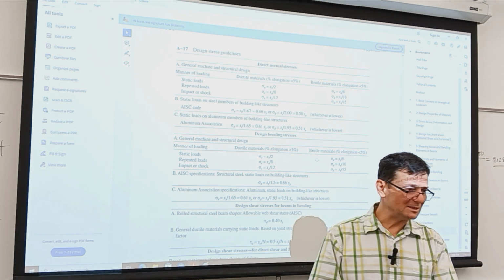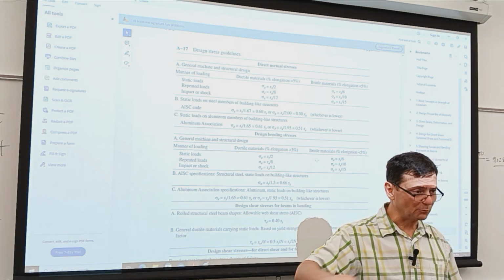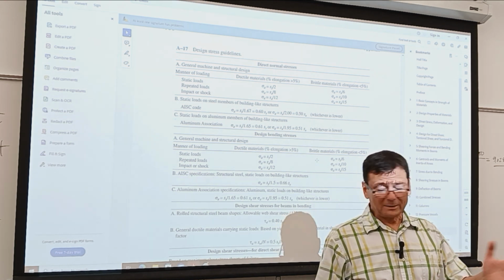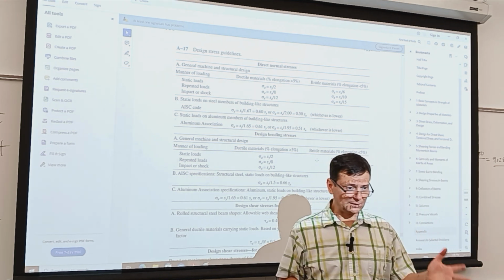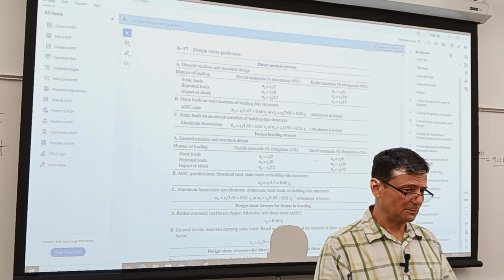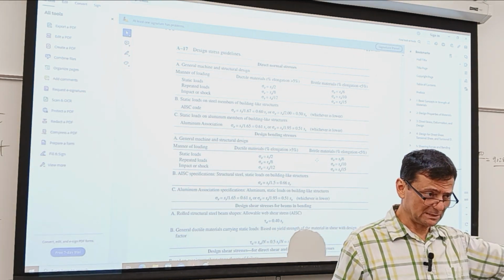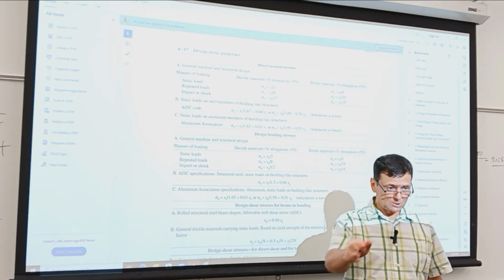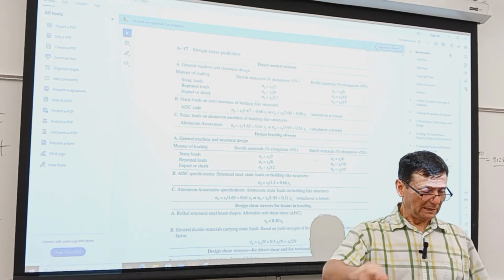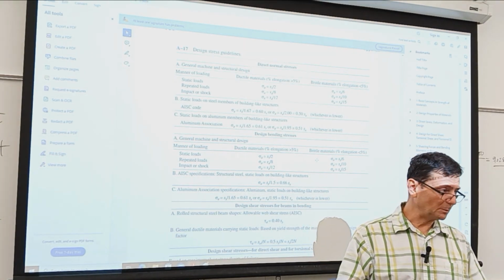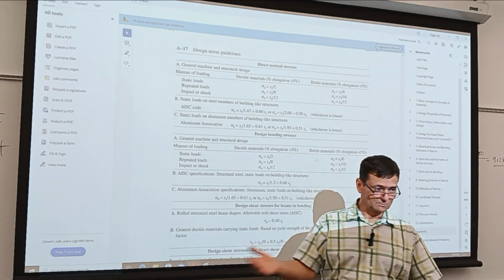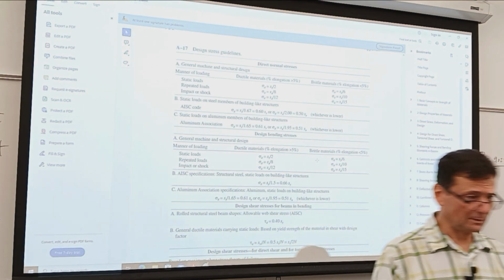But they have the means to verify. They do ultrasound to check for voids and cracks. I express some skepticism, but they know what they are doing. There's a full industry, not some small business that wants to make money taking people under the water. So they do ultrasound testing in areas that are known to be stressed, and they're probably going to replace the part if possible, or just declare this is the life of the airplane.